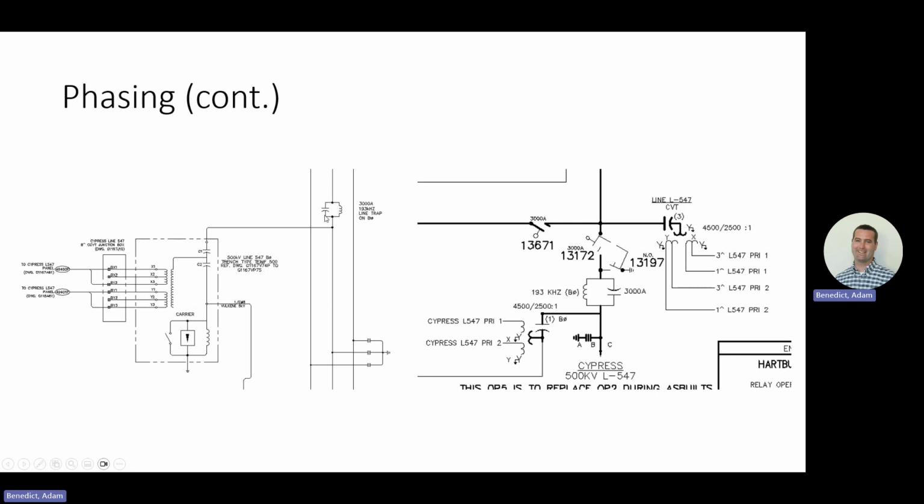So this is a traditional 3-line AC schematic. And here, what we're looking at is our wave trap. It's typically on one phase. Here they chose the center phase B, and what we're going to look for is, it's not shown here, but making sure that's on phase B, as it says right there. So I'd be looking to say, okay, A, B, C, that's on B, that's great. And then I'd double check the EA as well.